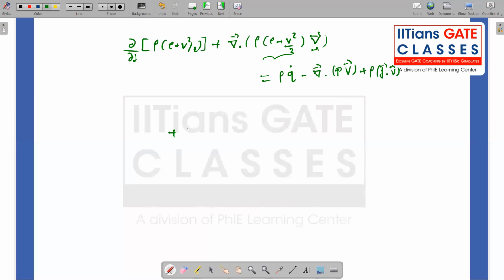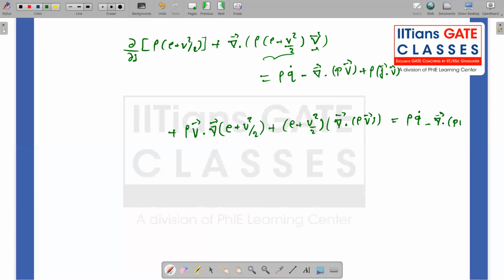So that is rho times the velocity vector dotted with the gradient of (E plus V squared by 2), plus (E plus V squared by 2) times the divergence of rho V, equal to rho q dot minus the divergence of pV, plus rho times F dot V.